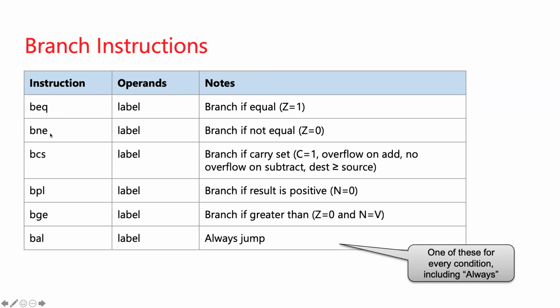It's because those two characters are used in all of the branch instructions. So BEQ branches if you just did a comparison that was equal, effectively if the Z flag is set. BNE is the opposite, and this is just a sampling of them, but they all use names from that previous chart. So branch if carry set, and they all take as an operand a label, just like Intel, where do you want to jump to?